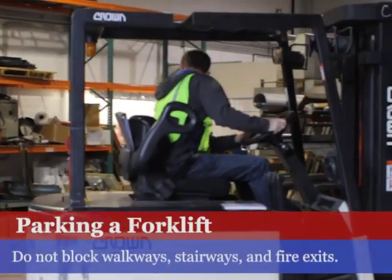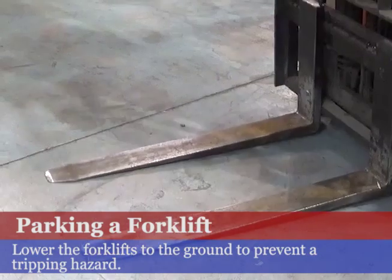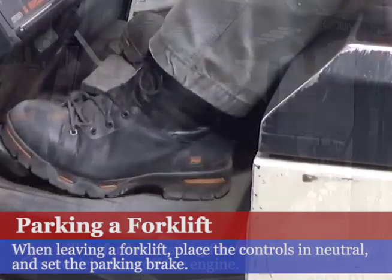When parking a forklift, avoid blocking walkways, stairways, and fire exits. Lower the forks all the way to the ground, to eliminate a tripping hazard. Before you exit the forklift, put the controls in neutral, and set the parking brake.